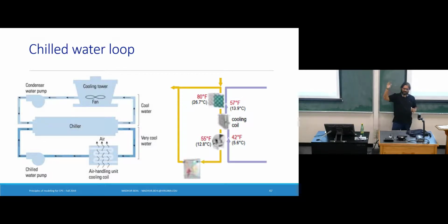Okay, so we've come all the way from every room now to this massive equipment called a cooling tower, which is utilizing the property of mist of water falling a certain height at a certain speed regulated by a fan to reject that heat to the outside world. And so it cools that water down, that water goes back into the chiller, picks up the refrigerant heat flow and rejects it to the environment again.